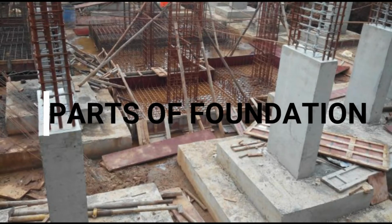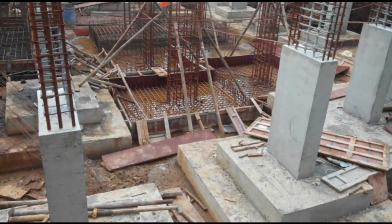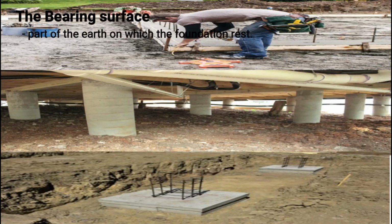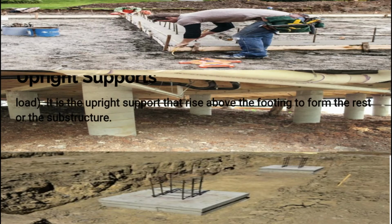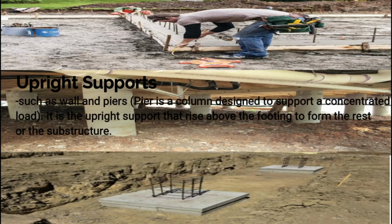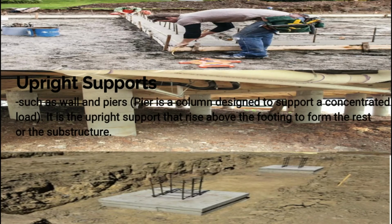Parts of foundation. A foundation can be divided into three parts. 1. Bearing surface is a part of the earth on which the foundation rests. 2. Upright supports, such as wall and piers. Pier is a column designed to support a concentrated load. A member, usually in the form of a thickened section which forms an integral part of a wall, usually placed at intervals along the wall to provide lateral support or to support concentrated vertical loads. It is the upright support that rises above the footing to form the rest of the substructure.